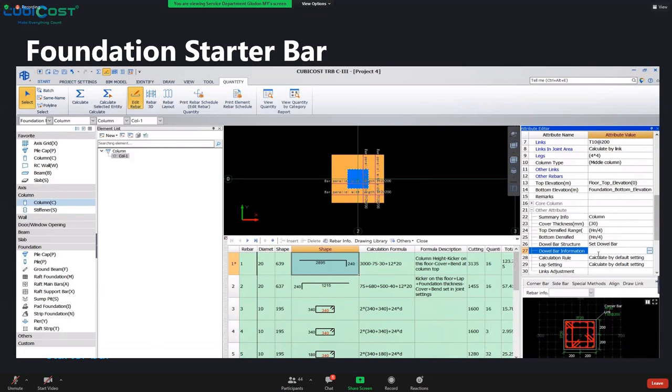Normally, what they will do is this. They will actually draw 2 columns first, to cater to this, because they want to have different bar types. Because we all know that in a single column, yes, you can key in 2 different bar types, but the arrangement of the bar is not up to what we want. So with that said, they draw 2 columns. And one more thing: why do they draw 2 columns? Because they want to separate out the quantity.